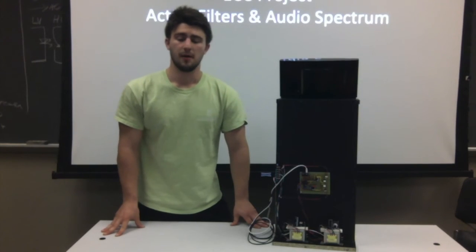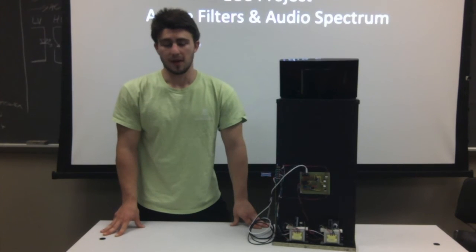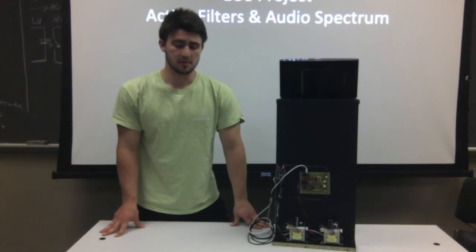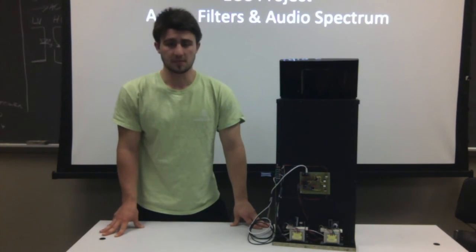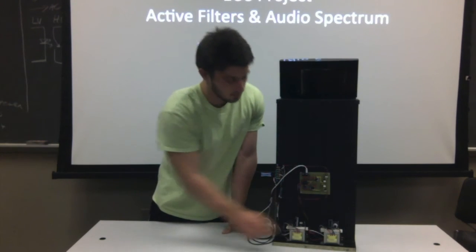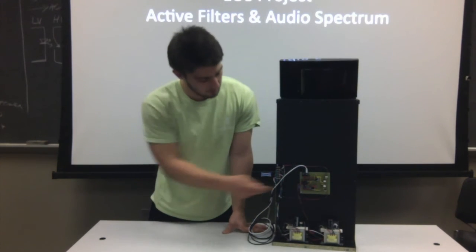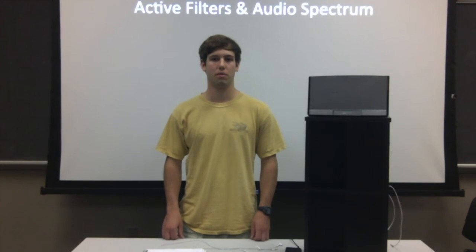To successfully power the components in the circuit, a positive 12 source, negative 12 source, and ground was required. This was accomplished using 2 12-volt power supplies connected to a common ground here. When the optocoupler receives 1.7 volts from the filters, the triac switches on and turns on the lights.